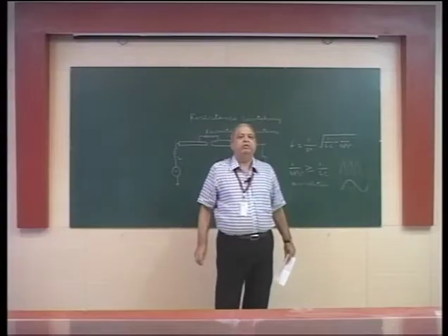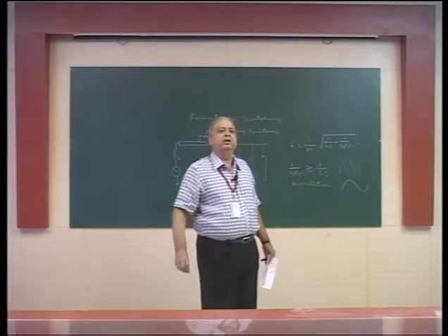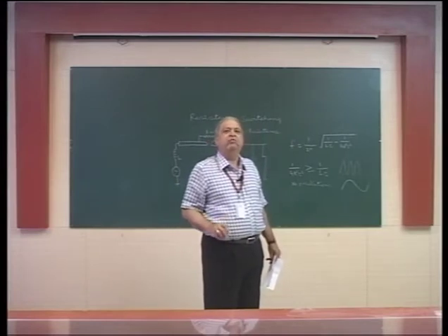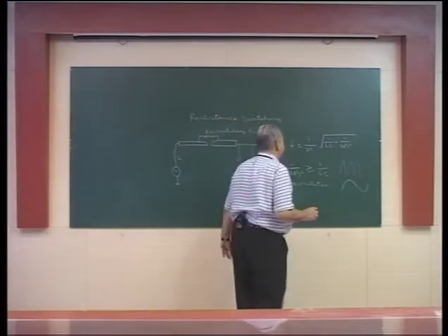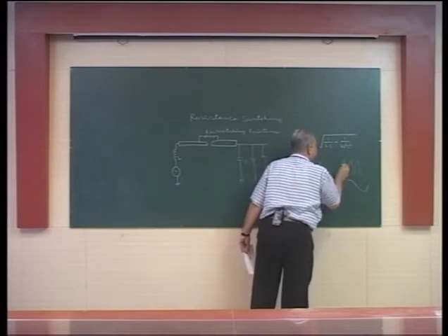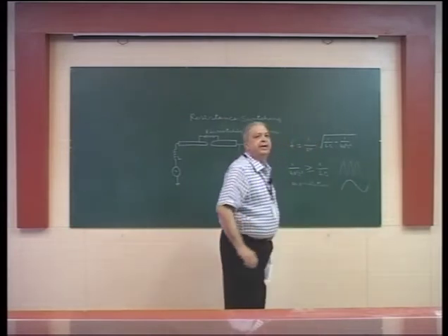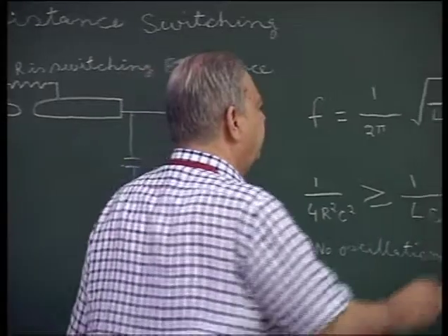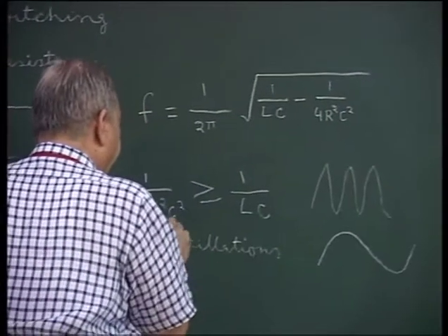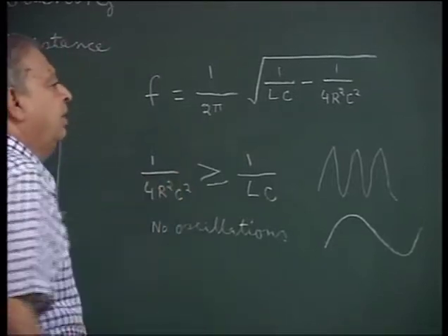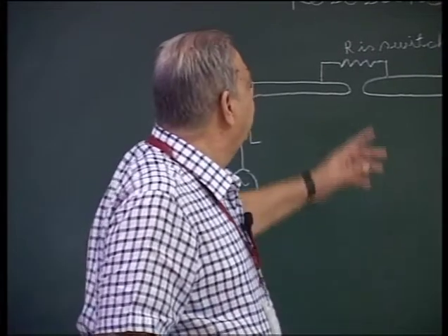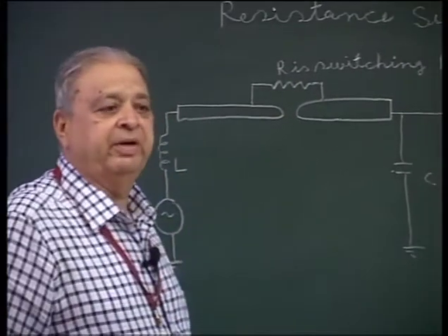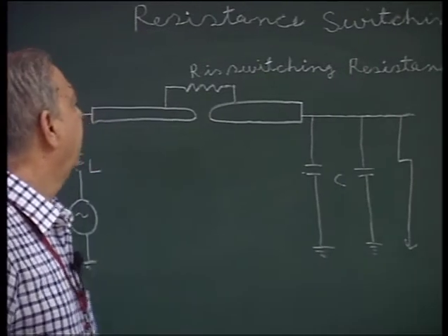So power frequency rise of voltage is not much responsible for restriking of the arc after the natural current zero. But the bigger culprit is the high frequency voltage, whose rate of rise is very high. And if this high frequency voltage is totally quenched by properly choosing the switching resistance, then the possibility of restriking becomes extremely low.